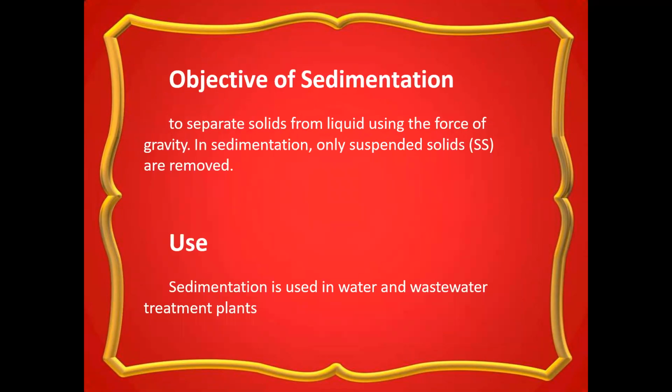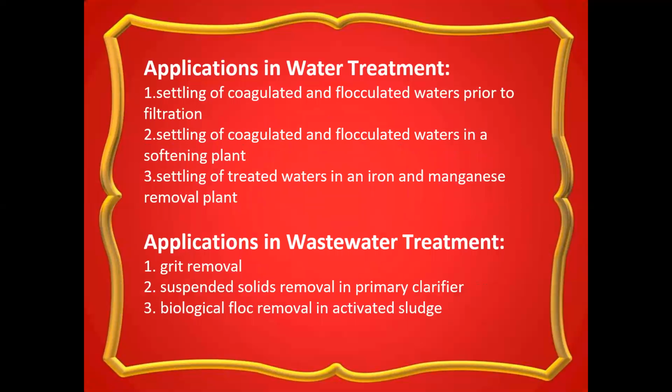Then what is the objective of sedimentation? It is to separate solids from liquids using the force of gravity. In sedimentation, only suspended solids are removed. Sedimentation is used in water and wastewater treatment plants.